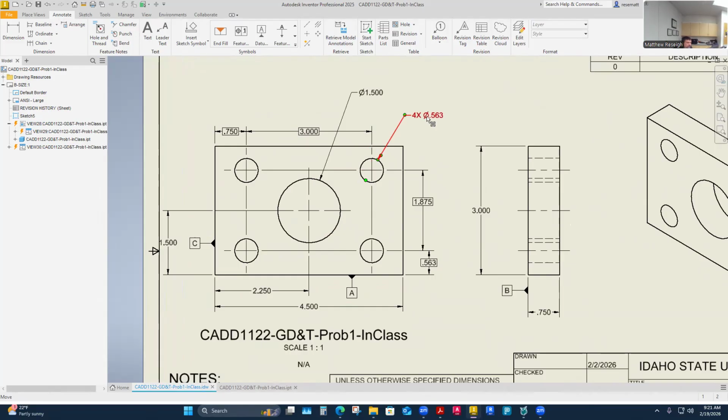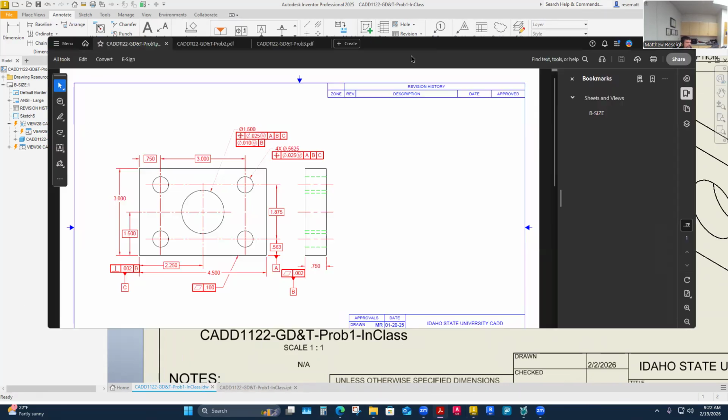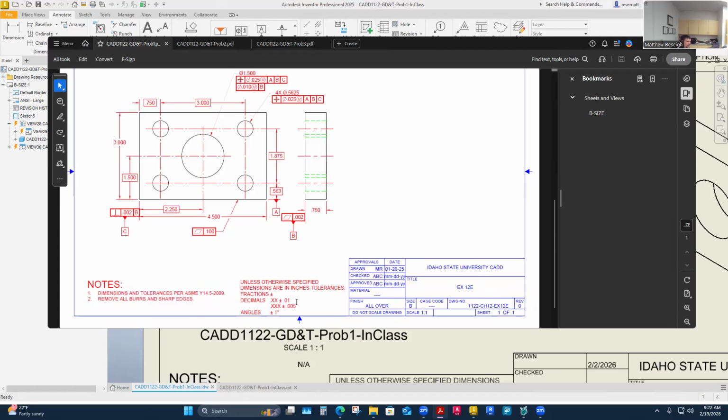So what I want to do is, I think it's really common. What I don't like about the old drawing, if I pull that up real quick, is that I think it's generally pretty common to have a tolerance on a hole. This one has no tolerance, other than I think we could still apply the tolerance that's here to even this dimension. I think I'm just going to display that. To me, I like that visual plus or minus dimensioning there on the hole size.